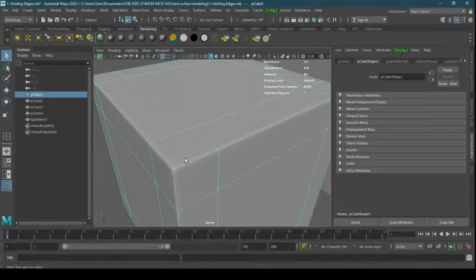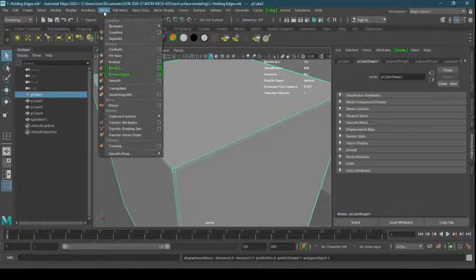But if you want to apply this effect for any other application, then instead of pressing 3, let me go back to 1. I have to go to Mesh on the top, then choose Smooth, and then it will do that. But right now, why am I pressing 3 instead of Smooth from here?